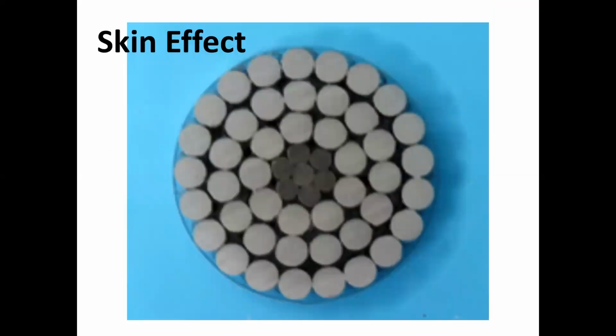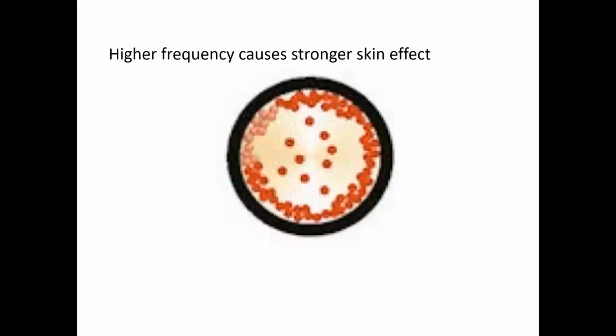We also have something called skin effect. And skin effect is harnessed in different areas because when an AC system is connected to a conductor, the current will want to flow on the furthest exterior edge of the conductor, which is why on many overhead lines, the center is simply steel, not only for strength, but also because very little current will actually flow in the center of the cable. And so that then means that we have less conductive material in order to carry the current. And that again would be an inefficiency and therefore a bit of a loss.